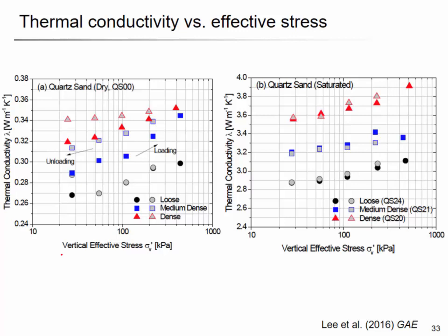So let's do this one first. I'll put this one like this, and then it has a power supply, and it records the data. Okay. So now I start to apply the 8 volts and the current is about 50 milliampere set here, and temperature is increasing like this. Now the temperature is 30. It's increasing. So you measure it over time. Generally, the measurement time takes 5 minutes. Then you can plot delta T versus log t, and then you can find the linear region and get the same curve that we've seen in the previous slide.